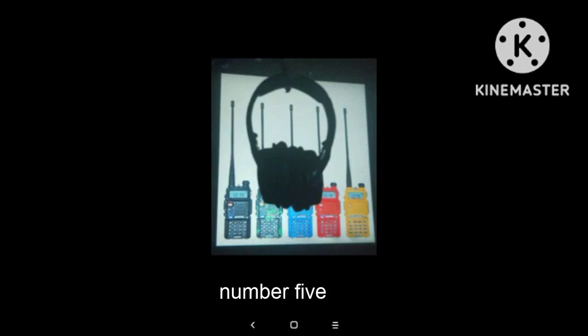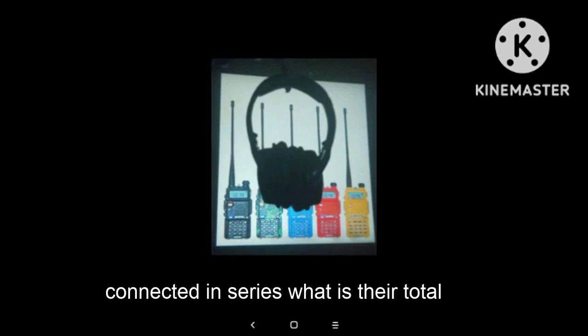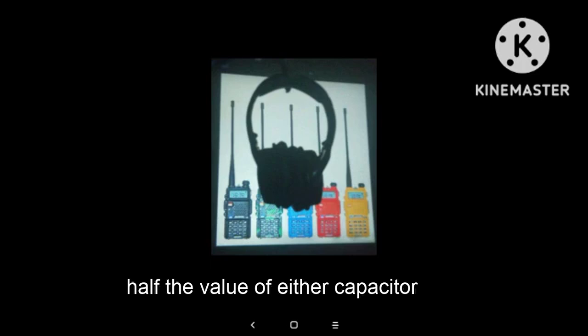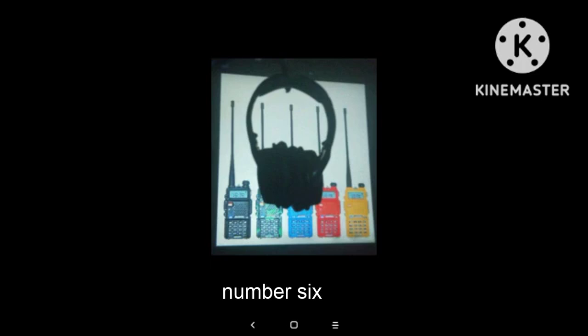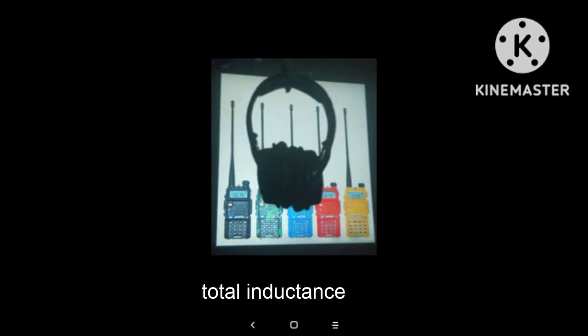Number 5. If two equal value capacitors are connected in series, what is their total capacitance? Half the value of either capacitor. Number 6. If two equal value inductors are connected in parallel, what is their total inductance? Half the value of one inductor.